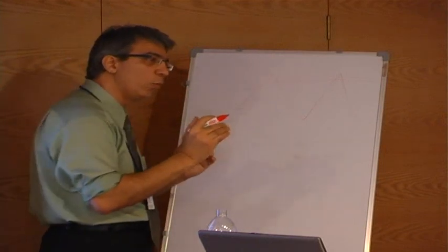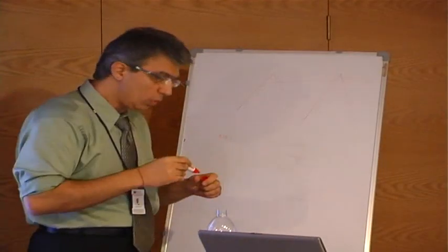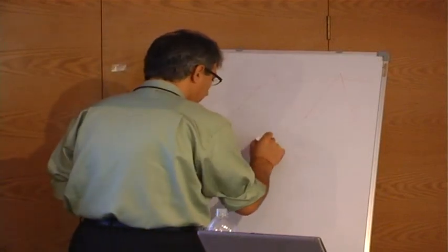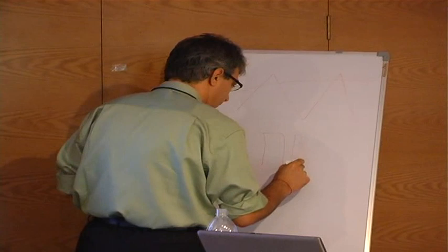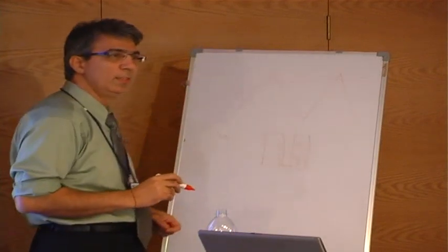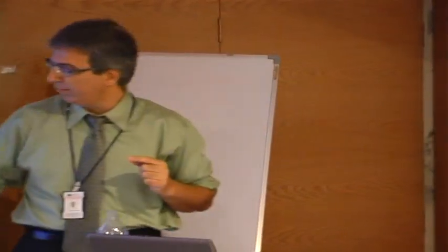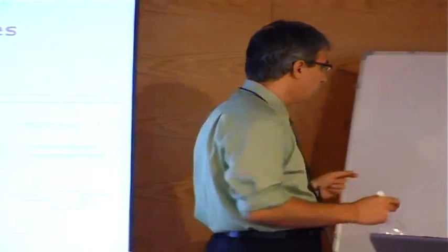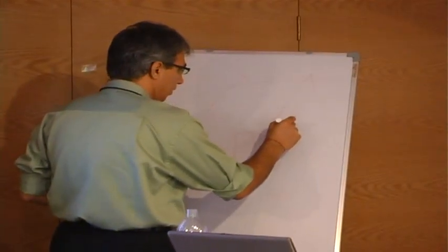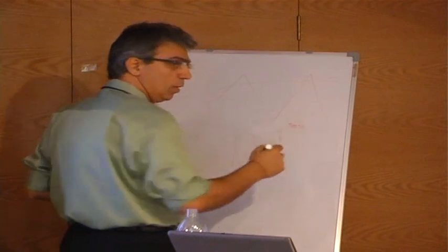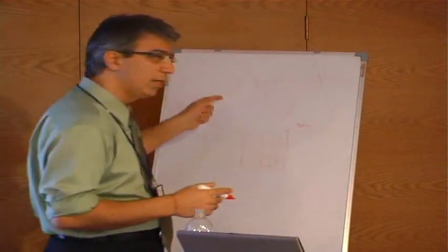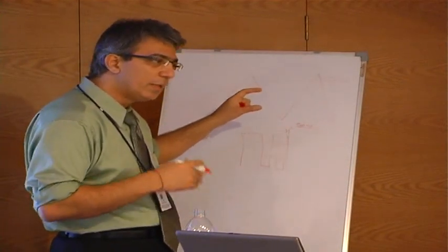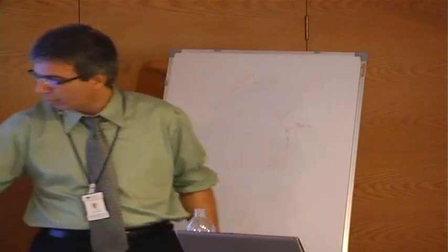Now, as it approaches 1, the gate drive pulses go like this, and they become very, very tiny. When they become very tiny, I run the risk of blowing the top back because I may not have enough time to turn it on. If I have a pulse of 500 nanoseconds and I'm using an IGBT, I'm toast. You can't turn it on very fast. So that's where it becomes significant, even for practical reasons, to have the limiter block even in this case.